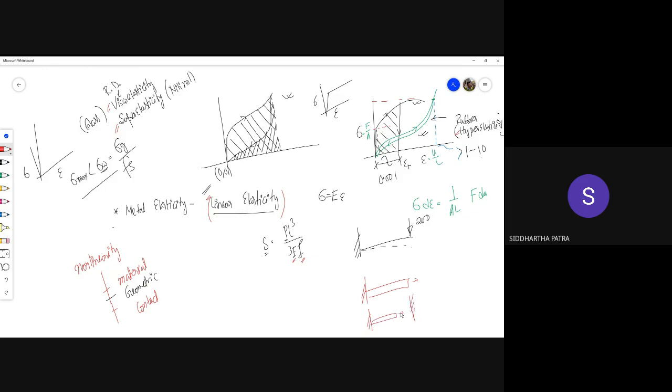If it elongates up to a certain limit beyond which it cannot elongate, because it comes in contact with the stop, here it could be showing a force displacement relation which is linear if we neglect the other two non-linearities, but here it would be something like this. If I imagine there is a rigid stop, then you need an infinite amount of force to cause any further deflection.